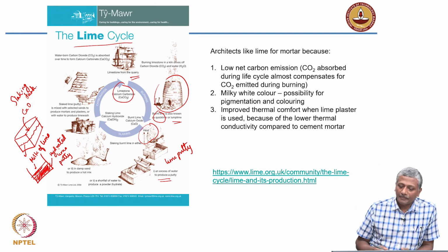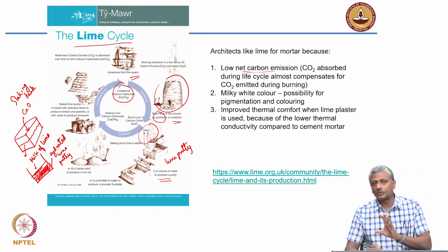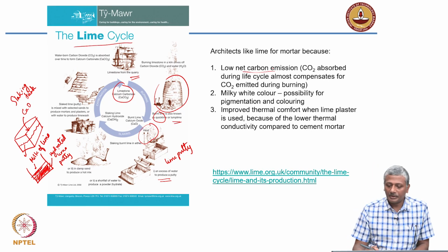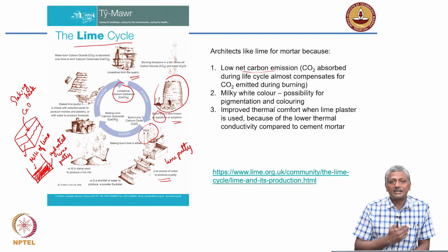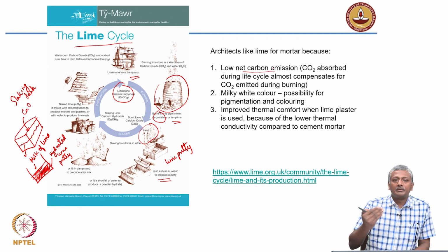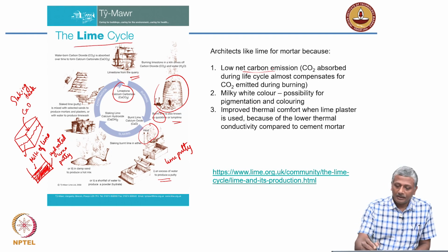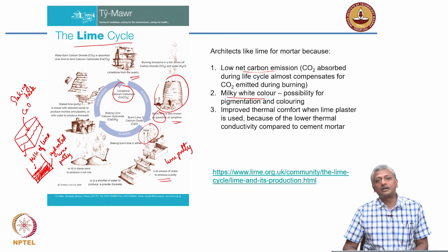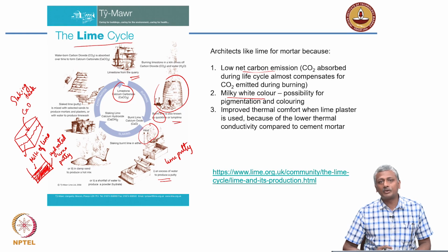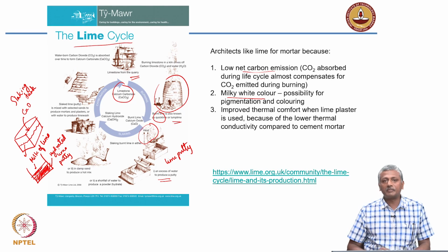So again, as I said, architects like lime for mortar because of net carbon emission being very low, not zero, it can't be zero, but it's very low. The CO2 that is emitted during burning, most of it gets reabsorbed during the process of hardening. Pure lime mortar will have a milky white color, and that's very good for pigmentation. You can color it in different pigments. So that's why architects like lime mortar.